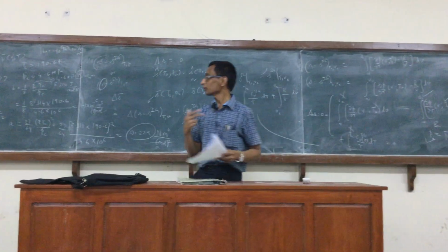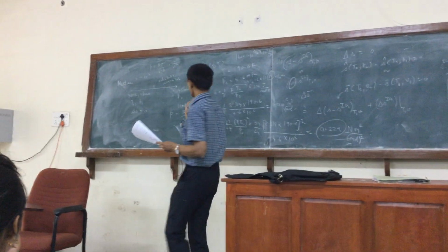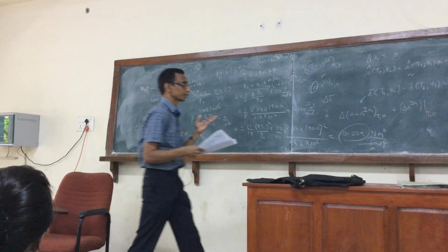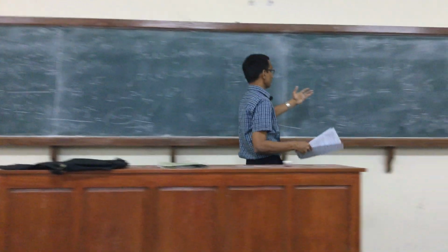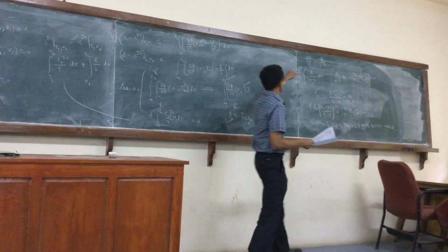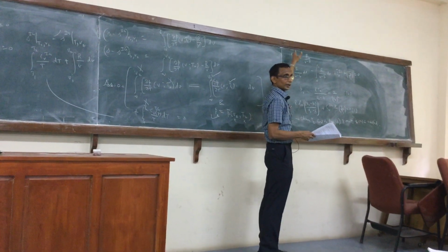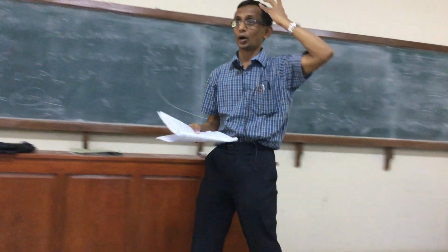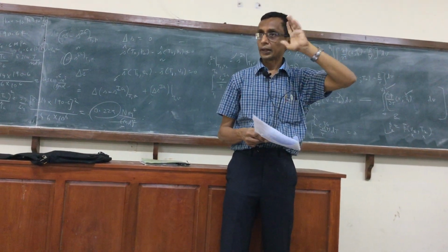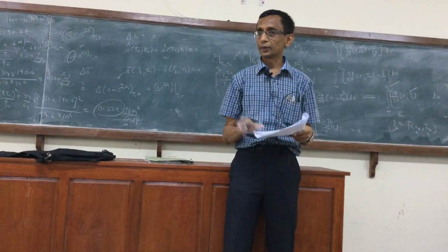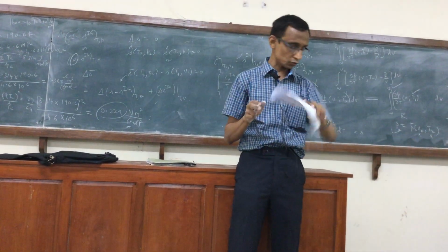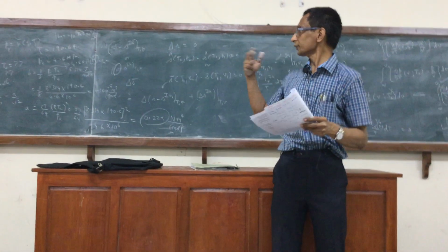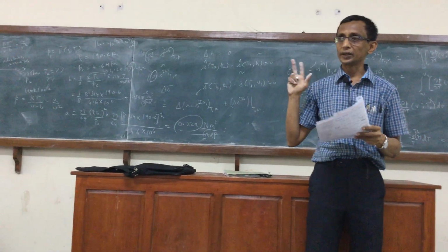Of course, if I had the SRK or the Peng-Robinson, then I would also have to consider that temperature is involved. So at a particular temperature, A would no longer be this constant; you get a temperature dependence, and that will depend on whether it is evaluated at T1 or T2. So you have to be careful. I am avoiding that problem by choosing the van der Waals equation of state. So the first step, clearly, is to find V1.